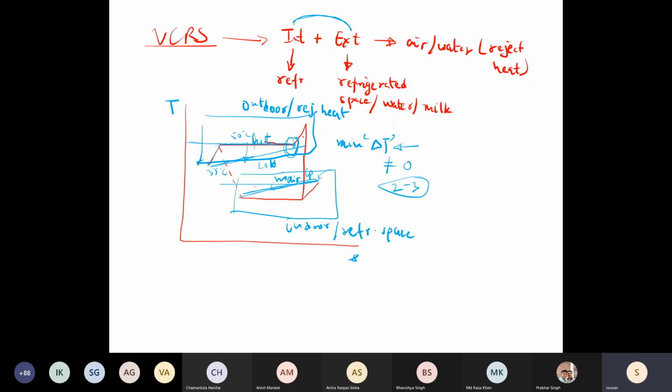So if you operate your heat exchangers in different conditions, because there is a connection between internal and external regime, your operating conditions on the refrigerant side will also change. That is the most important thing that we must understand. So the design or sizing of the heat exchangers is also critical. Most of the air conditioning systems that we use are typically designed for 52 degrees C. You will see that label. So this system can operate at even 52 degrees C ambient condition. So we are designing it for the most extreme case.